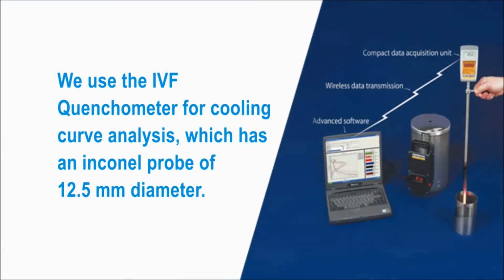We use the IVF quenchometer for cooling curve analysis, which has an Inconel probe of 12.5 mm diameter.